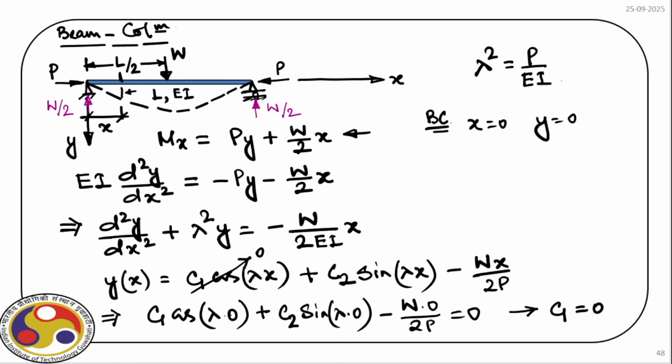Now, in place of W, which is a point load acting at the middle, we can actually have UDL, and then we can also derive the expression of maximum moment for the UDL. If you have UDL, the support reactions will be the intensity of the UDL, say omega, times L, that is the total load, by 2. And accordingly, you can write down the expression for this Mx.